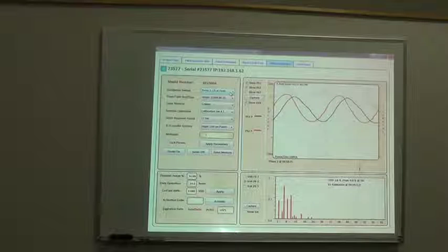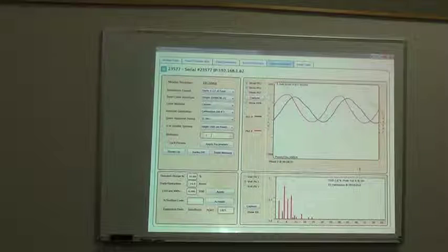If the load is nicely distributed in the panel, then great, put it on the feed side. But if it looks like one or two loads are the significant part of the panel, let's say there's two of them, then you should put the CT on one of them and make the multiplier 2. You know what I mean? That would basically mean that we're responding to both of them. On the other hand, if you have 10 different breakers and each one is responsible for 5 to 15, 20%, then put it on the feed, and that's what it's designed to do.